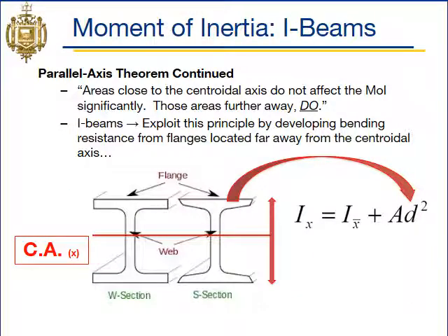So we typically use in this class that table and the parallel axis theorem to calculate the moment of inertia of I-beams. Right, and so why are I-beams great as structural members? Well, they take advantage of the parallel axis theorem. Specifically, this d squared function.